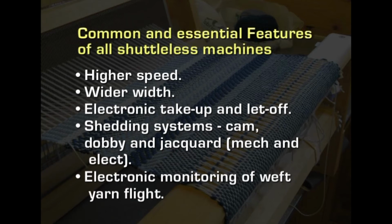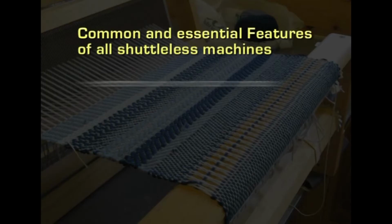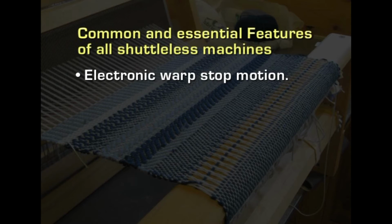Then you have the electronic monitoring of the weft yarn flight. When the weft yarn goes from one end to the other, there is electronic monitoring. If there is any breakage, then it will be notified, the loom will stop, and then immediately the mending of the yarn can be done and the loom will again start working. Then you have the electronic warp stop motion. If in case the warp yarn breaks, then there will be the immediate automatic stoppage of the loom. The warp yarn can be joined, the ends can be joined, and again the loom will start.